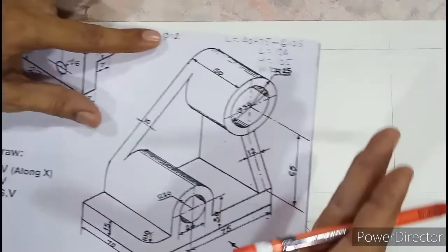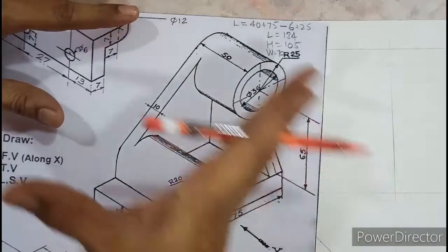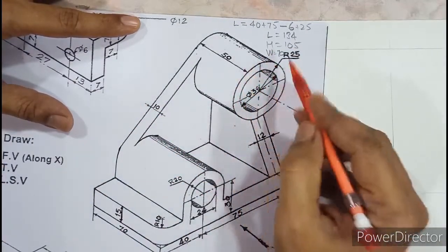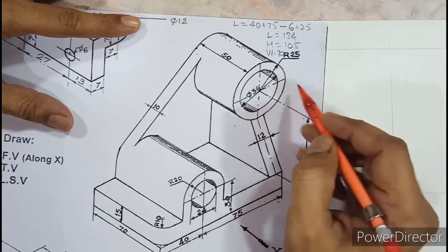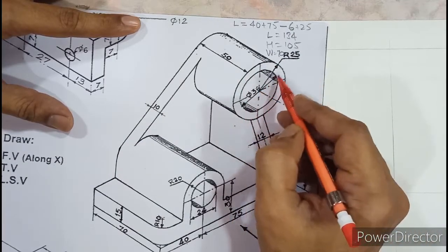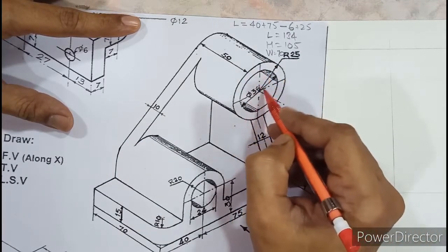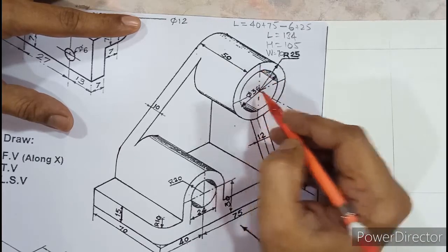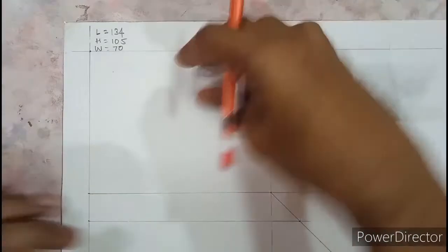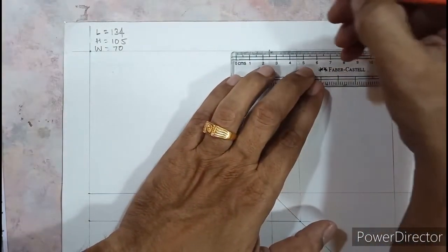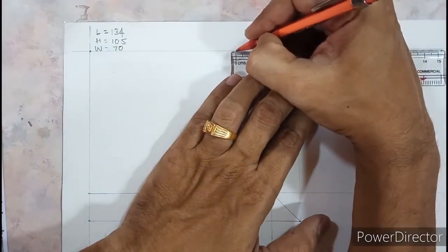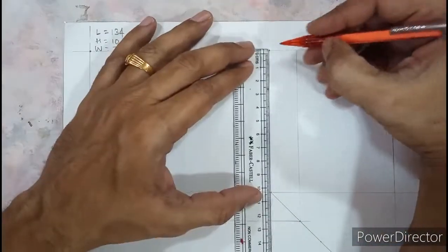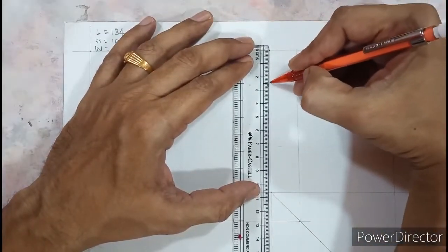Okay, so if you try to visualize from the front and compress the object, this circle is on the extreme top, isn't it, and on the right side. So let us locate the center of the circle by marking 25 from either side. So from this boundary it is 25, from the top boundary it is 25. Let us quickly mark the center, say this is 25. For another center you have to come down by 25, so you have to mark 25 down from both the sides.